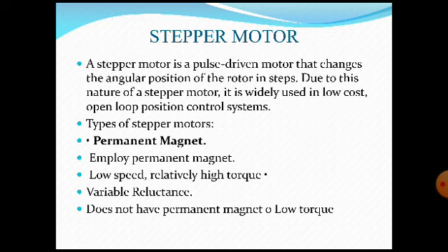As the name itself indicates, these motors are made to rotate for each pulse, to a minimum angle of 7.5 degrees, which we discussed if you recollect, in considering the actuation systems in mechatronics. The stepper motor is rotated as per the electronic pulses generated from the controller unit.